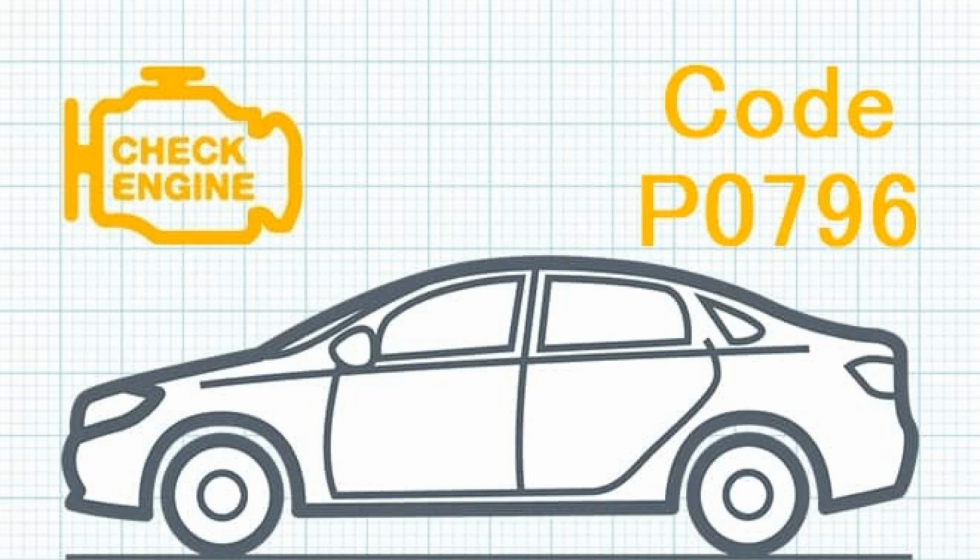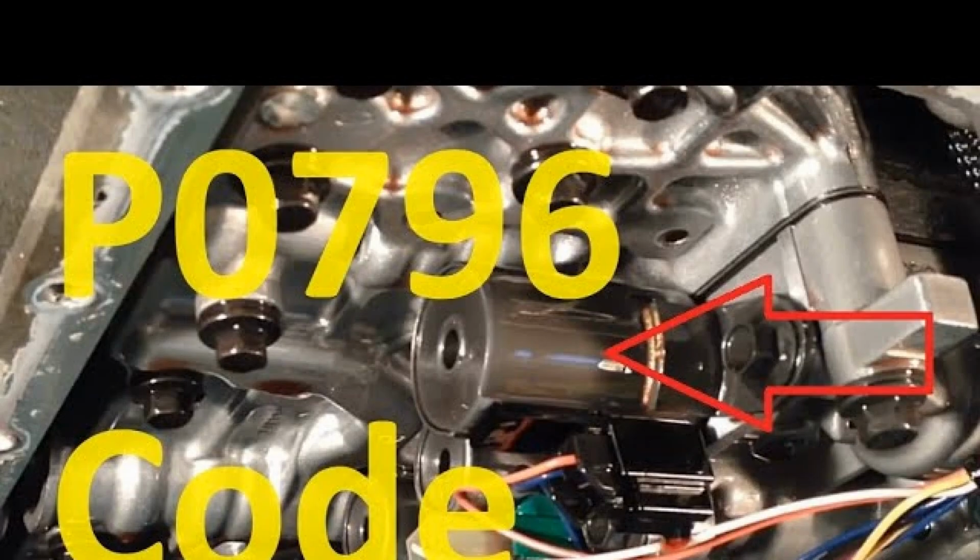This diagnostic trouble code, DTC, is a generic transmission code. Error P0796 is considered a generic code as it applies to all vehicle makes and models, although the specific repair steps may vary slightly depending on the model. The P0796 OBD2 fault code is set when the control module, PCM, detects a problem with the C valve of the transmission pressure control solenoid.